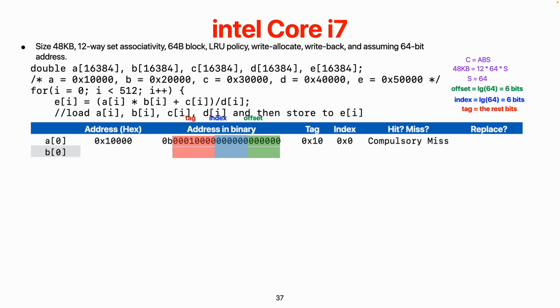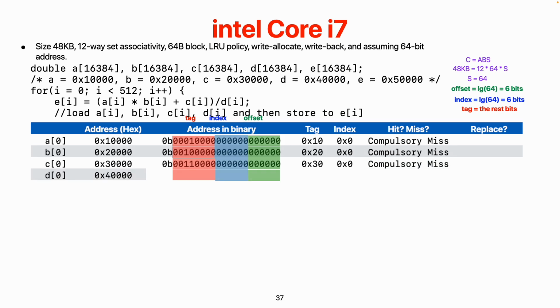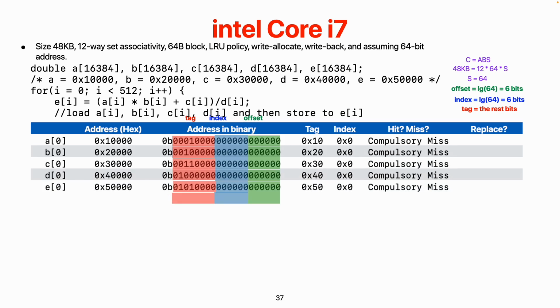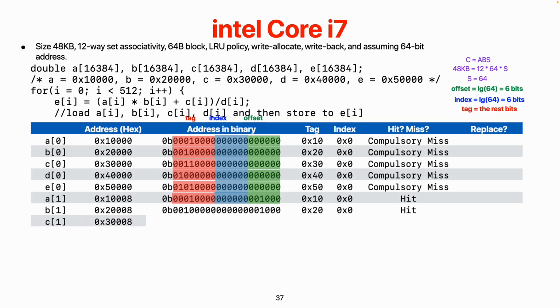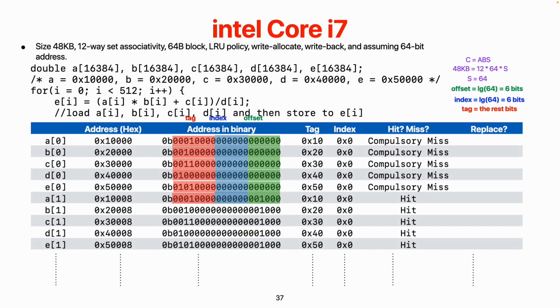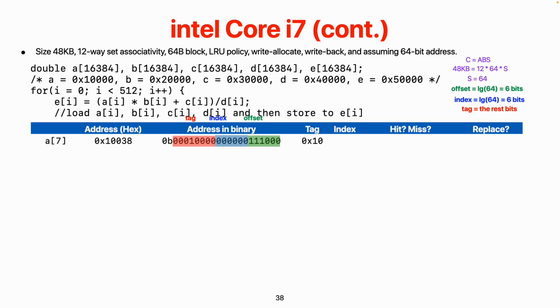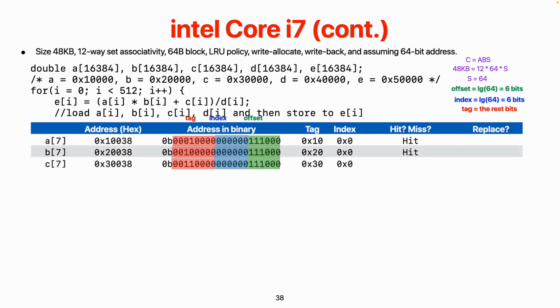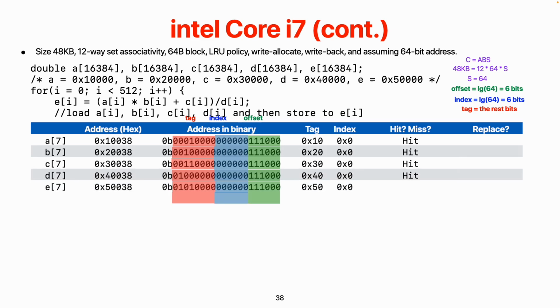So if you look at the sequence, the only misses we are having is when we enter the boundary of a new block, and that's always the first time we visit the first element within a block. Everything else is a hit. So the remaining misses are just compulsory misses. If I give you this piece of code and an Intel Core i7 processor, what mechanism should you use to optimize it? You should come up with the idea that what I need is a mechanism that can remedy compulsory misses. That's why we want to do this analysis and figure out the main source of misses in any kind of software that we need to optimize.